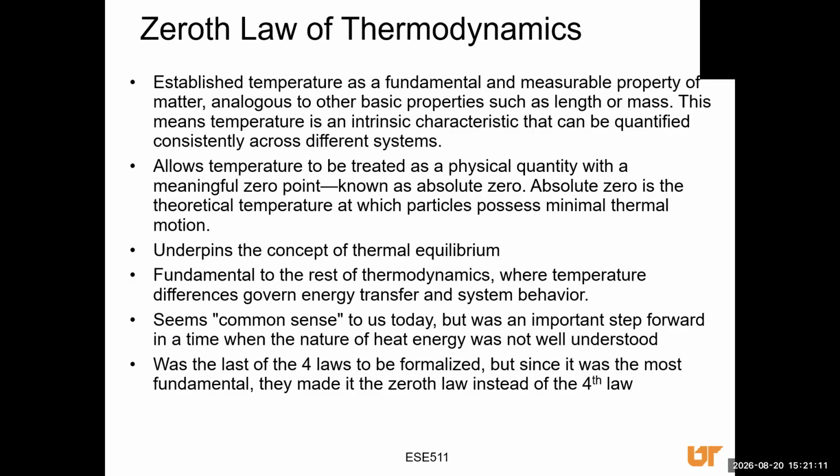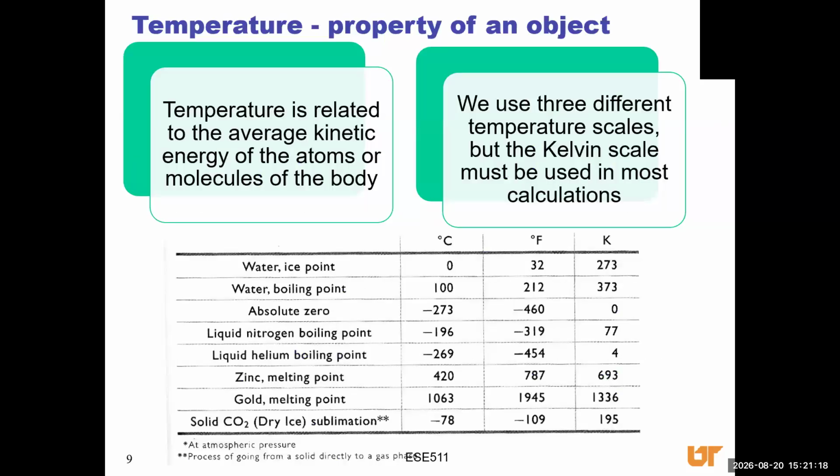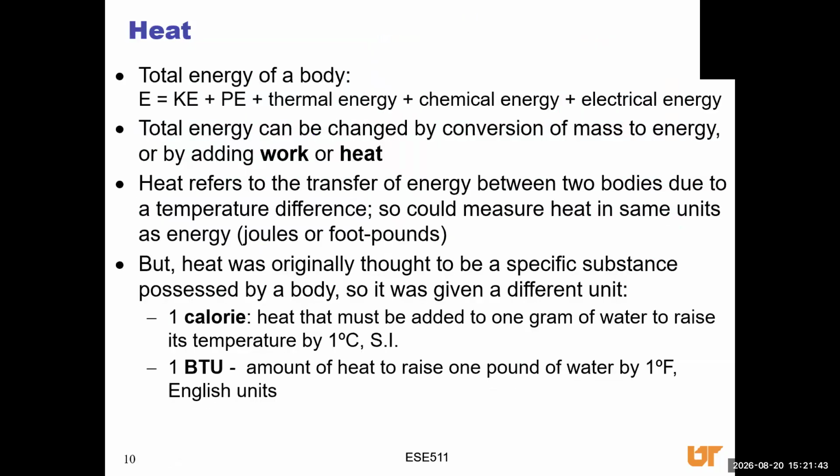Here's some more details about the zeroth law of thermodynamics. Don't need to beat that particular horse. We know already, and have long been using, all of us, the different temperature scales. And just remember my suggestion that whatever temperature I give you for anything in any problem, or not just a homework problem, just over your career, anytime you're given anything in any temperature scale, convert it to Kelvin before you start to do calculations. And that will prevent accidents and errors.